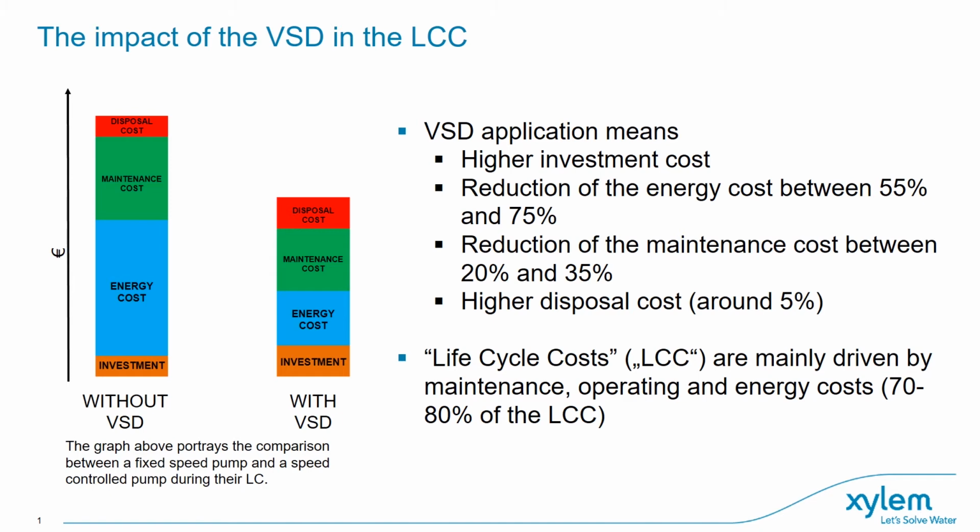We have less water hammer going through the system, because if you compare to a traditional fixed speed installation, when a pressure switch would traditionally ask the pumps to switch on, there would be a significant surge of pressure going through the pipework.